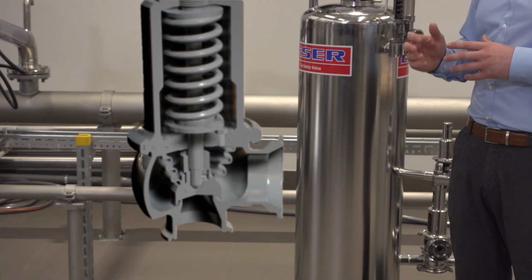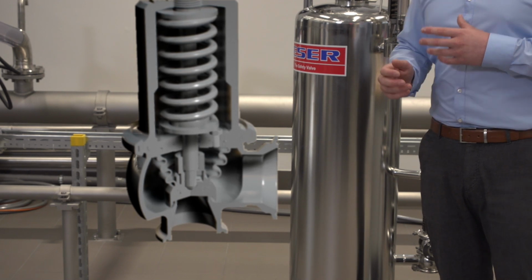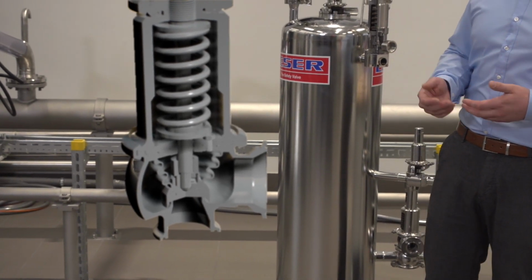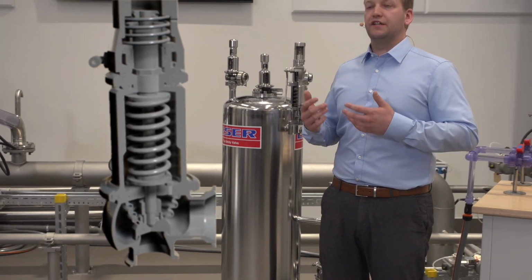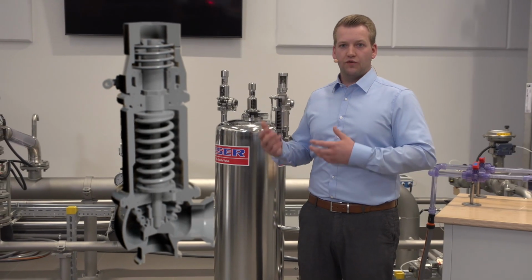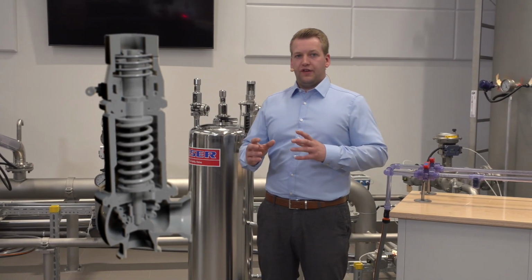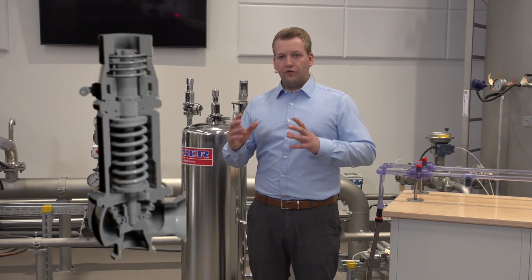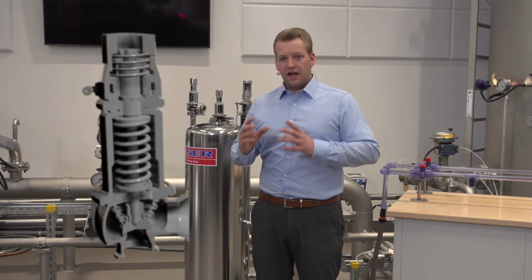So in the inlet we have a very small dead space ratio, roughly 1.5. You can start a very efficient cleaning process with this clean service safety valve. If you have a dead space ratio over 1.5, there is a problem of a dead leg.